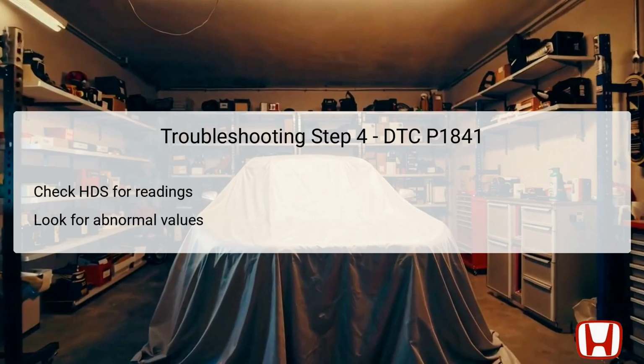This troubleshooting step is critical as it directly correlates the operational performance of the CVT speed sensor to the readings processed by the TCM. A reading other than reverse indicates a malfunctioning sensor or TCM that needs further investigation. It's important to document all readings during this step, as they will guide subsequent actions in the repair process.